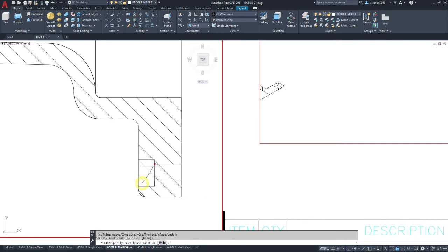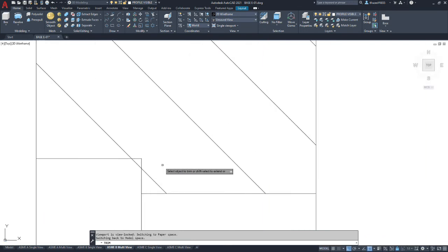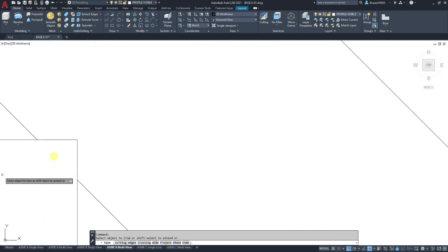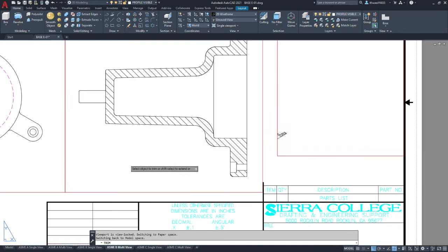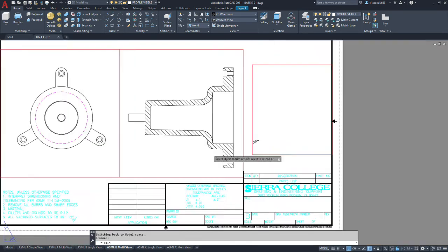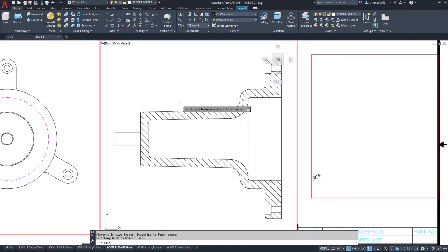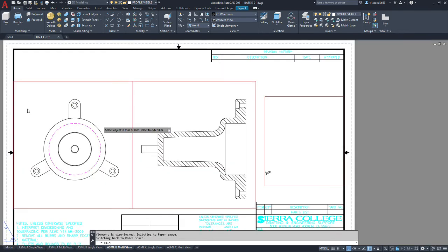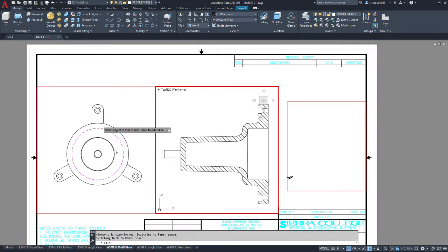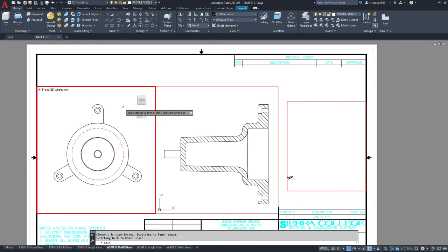And we'll do a power trim inside here, and another one inside there. And we got one little segment that needs to go away there. Now this reflects what you would see in an aligned view with a cutting plane like we're going to draw over here on the left.